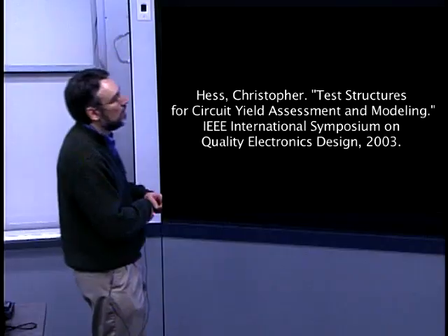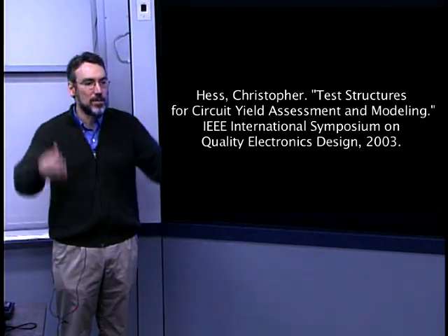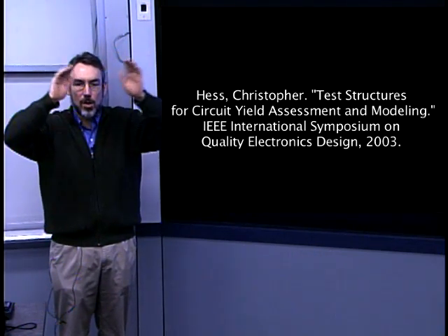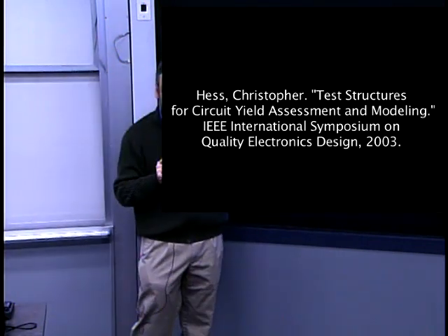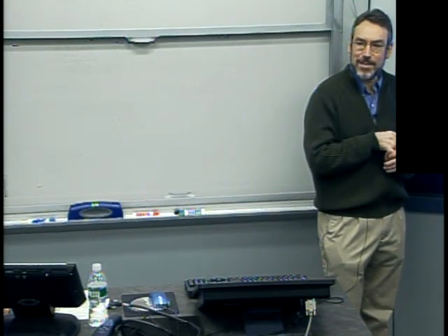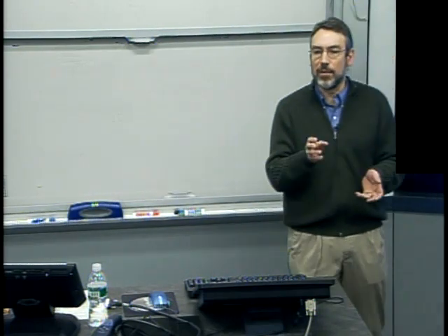And so that's why if you go into an IC fab, it's a clean room, everybody's wearing clean room garments, there's incredible amounts of airflow to filter out and remove all kinds of dust particles or other extraneous matter down to very, very tiny dimensions. That's really the measures that have been taken in order to get the cleanliness you need in order to not eliminate, but get those particles down to a particle density and down to a size that are small enough not to have too big of a yield impact.